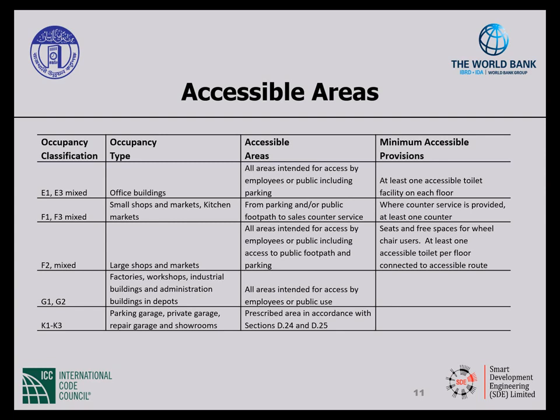For small shops and markets and kitchen markets, provide accessibility from parking and/or public footpath to the sales service counter, and where counter service is provided, at least one counter shall be accessible.